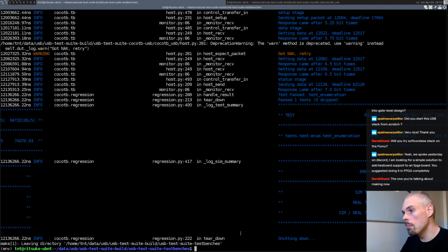That's actually one of the main reasons for the FOMU or the upcoming Bitsy: to have a very minimal code that you can easily just add to your design with no dependency or whatever. You just drop in a few Verilog files, and then you get basically a FIFO in and FIFO out port where you can easily read data in and out without having to mess with anything, and it just works.